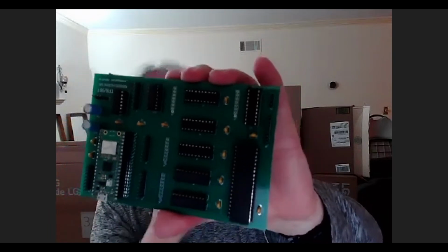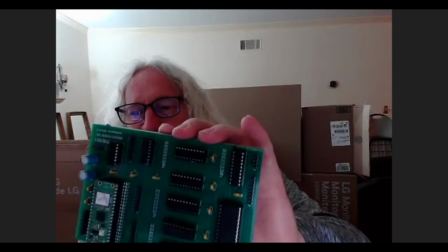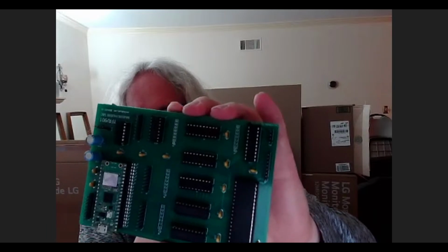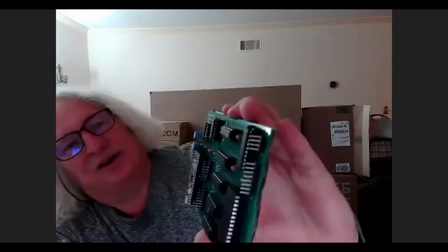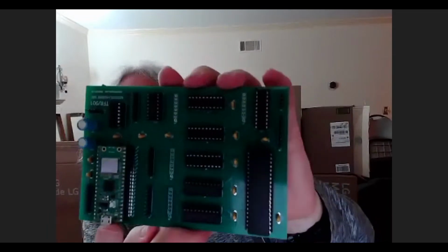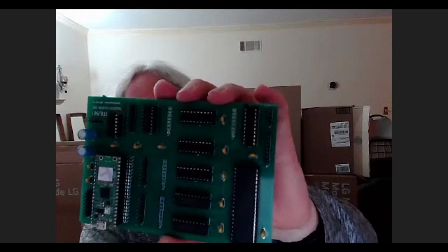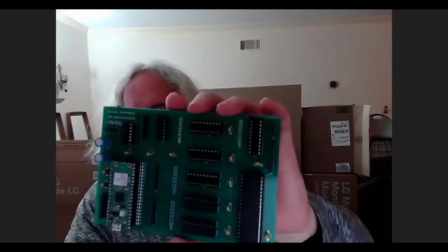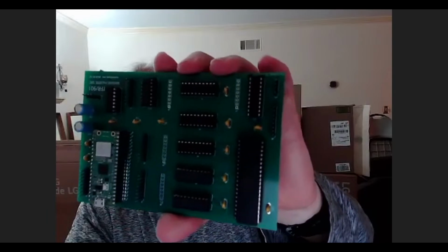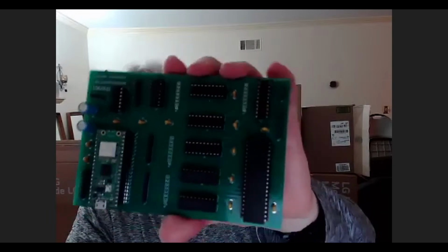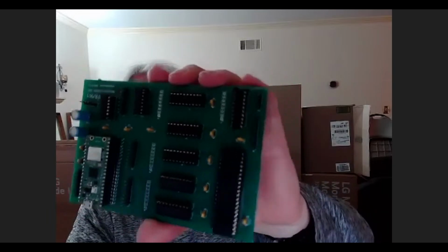The C means it's a 3 megahertz part. The E means that the clock is external, and that's going to be very important in this design. And on the other side, a Raspberry Pi Pico. And there's 8 glue chips on here. Since this was my first board and I was still in experimental design and debugging, everything is through-hole technology. So I did all the soldering on this one.